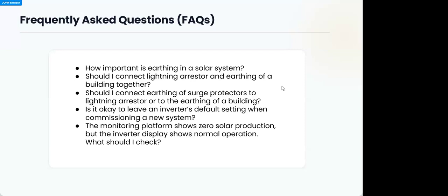You will not be allowed if communication is properly established. If you are sure it is communicating, then the inverter will not allow you to set it, because where it's going to charge to, where it's going to rest, or the amount of current it is going to demand is inside the brain of the battery, and it is sending it through the communication cable to the inverter: this is the way you should treat me. This is what I want.